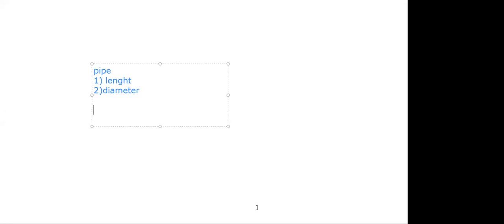So the node parameters now are the elevation of each point, which you get from your surveyor or from your survey data. You need a survey data, definitely. Number 2 is the demand. And I said this demand can also be called the flow. The flow, it can also be called the discharge. I think the discharge will basically come when you are doing something like stormwater or runoff. You use the word discharge, but they mean the same thing. In water reticulation, you call it demand, or you call it the flow of water at that point. They mean the same thing, and all of them are simply represented by Q.